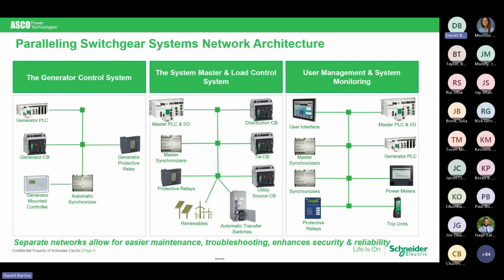If you do not have all of your generators of the same pitch, you are going to have circulating current that we can attempt to minimize, but we will not be able to remove it completely. So if you are adding a generator to existing generators, please work with your manufacturer to be sure you have the same pitch.